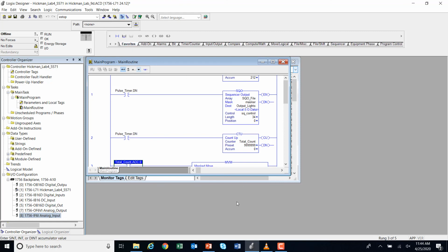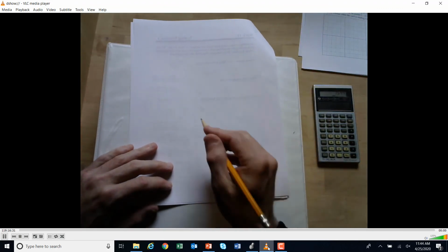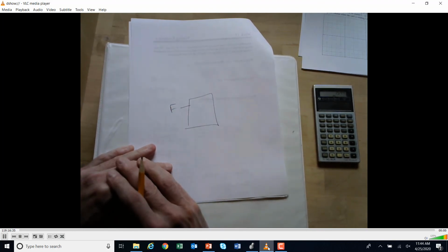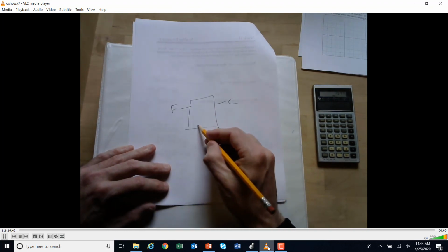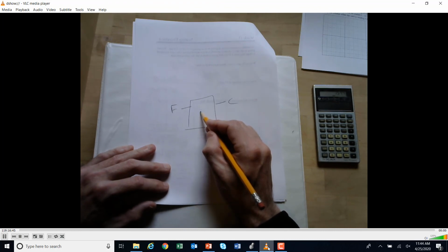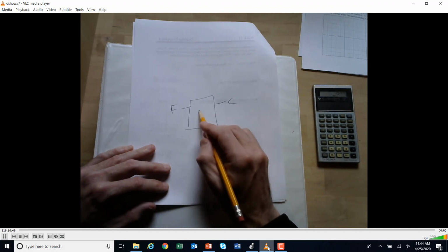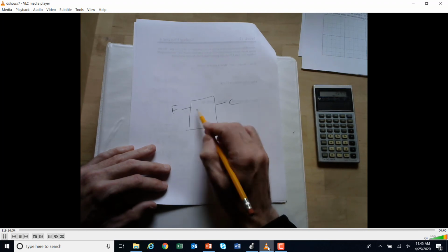And so how does that work? Well, the add-on instruction for Fahrenheit to Celsius conversion basically looks like a function block, and on this side we have Fahrenheit coming in, and on this side we have Celsius coming out. So what's going on in here? Well, inside of here there's some logic, and it's going to be to convert Fahrenheit to Celsius, or Celsius to Fahrenheit, you're multiplying or dividing by 5/9, and subtracting or adding 32, and that's that little formula, okay?